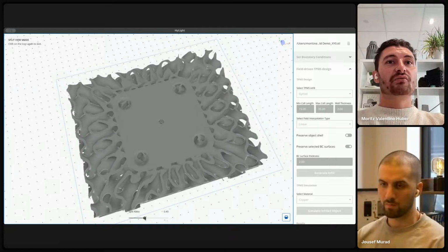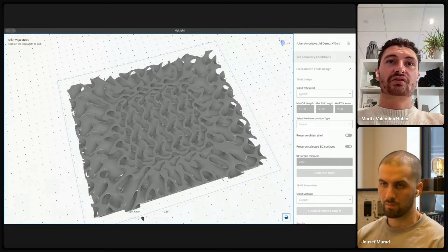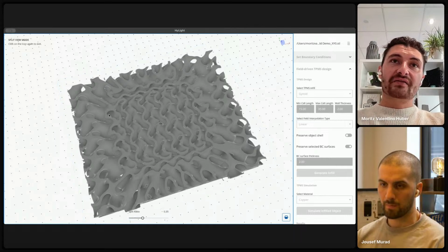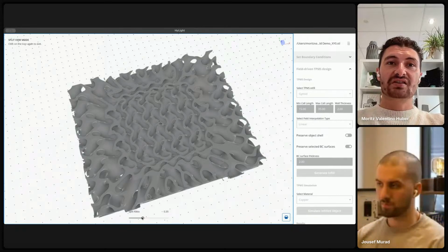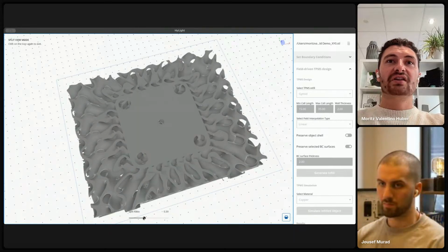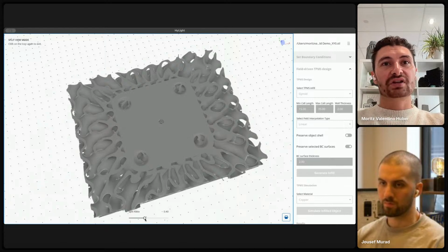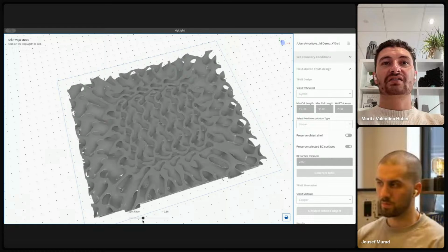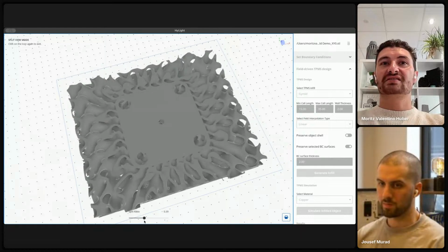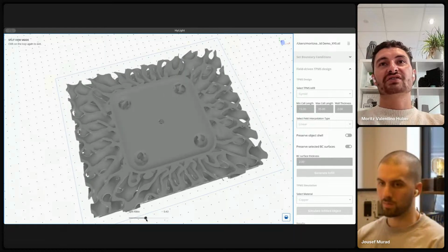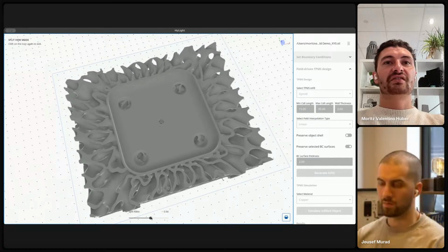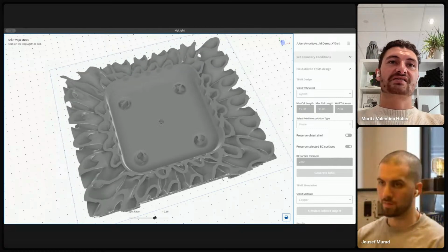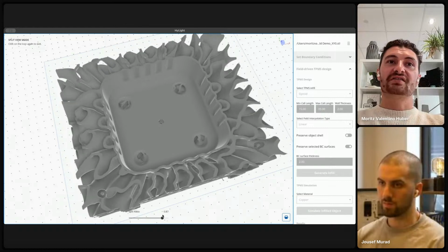You can see that wherever the heat load is the highest, the gyroid structure is also the densest. Especially here in the kink of the mold, where you would expect thermal stress concentrations, the structure is also the densest. So this porous gyroid structure is here as dense as nowhere else in this mold.